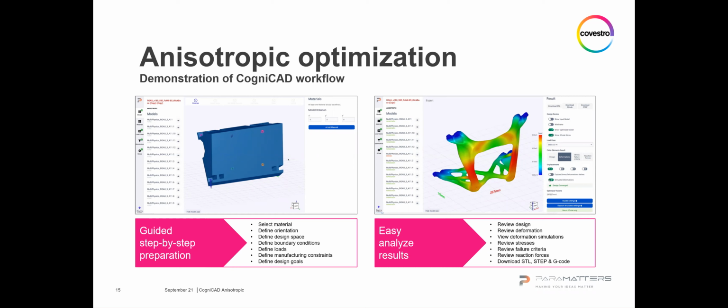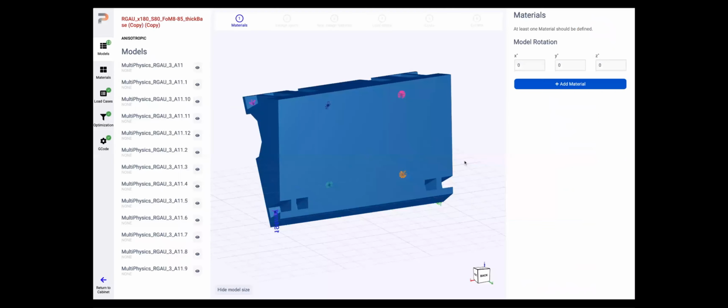So when we design a part, we have interfaces where parts should be mounted as a part of the assembly. Those interfaces should be preserved, untouched, and we create a design space, the maximum available place where the part can live. We do it in any CAD system and import it as a STEP assembly into the ParaMatters environment. So once the part is imported into ParaMatters software, Bram, if you can run the video, please. So once we have this assembly,